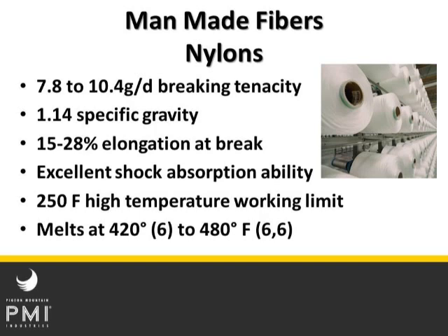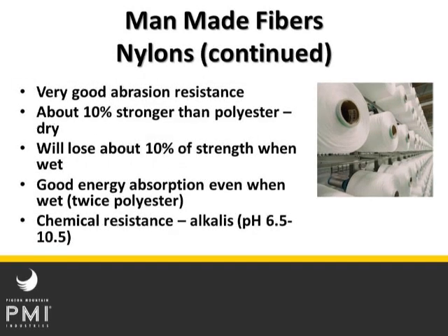More about nylon. It has good abrasion resistance. It's about 10% stronger than polyester when they're dry. It does lose 10% of that strength when it gets wet. Nylon gains it back when it dries out, but it'll be 10% less strong than the numbers that you will see in the catalogs when it's actually wet. It has, like we said, really good energy absorption even when wet.